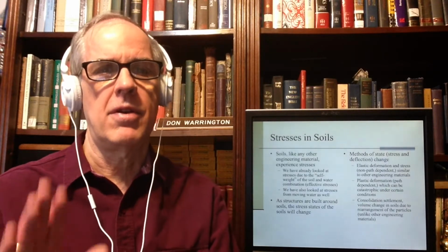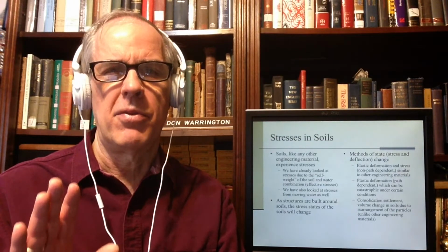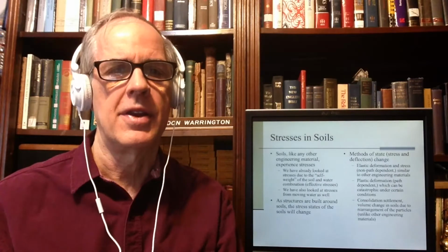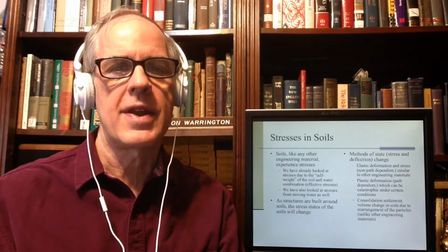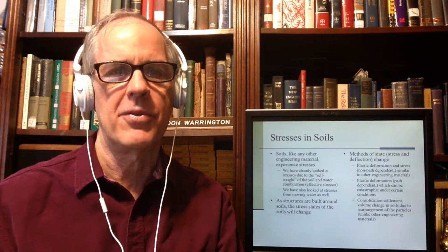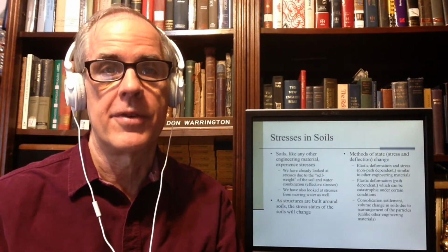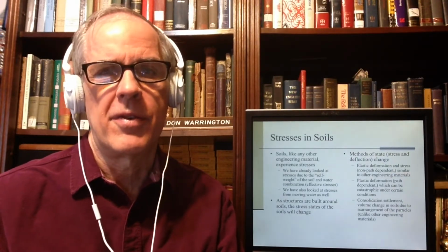Now, just don't spread this around, but with soils, there ain't no such thing as real elasticity. In rocks, you see it. In soils, not so much. We can see practical elasticity, and we're going to talk about practical elasticity, but not real elasticity. And it's not the only engineering material that experiences that problem. Cast iron is the same way, for example. It does not have real elasticity, and there are other materials that don't either.